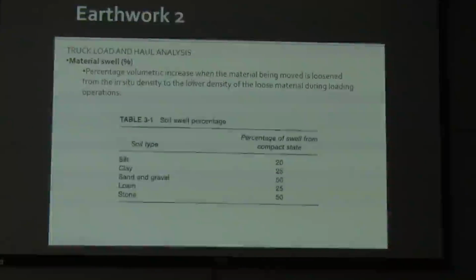Material swell is the percentage of volume increase when the material being moved is loosened from the in situ density to the lower density of the loose material during loading operations. Again, we looked at swell percentage. The swell is pretty much the inverse of the shrinkage factor. Again, these are based on local conditions. These are not universal swell values.